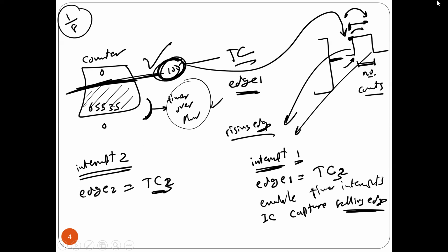So now I have H1. So I have the count here and I have the count here. A number of overflows already counted by the timer interrupts. I'm gonna talk about this. Forget it for now. Okay. Say what else I should do after doing this one. What else? What you have to do is I have to disable input capture. Okay. Number 1, why should I disable input capture? Simply because I already got H1 and H2.